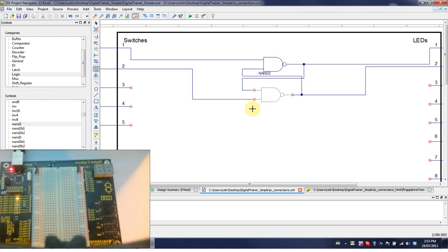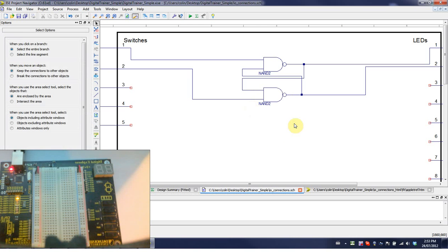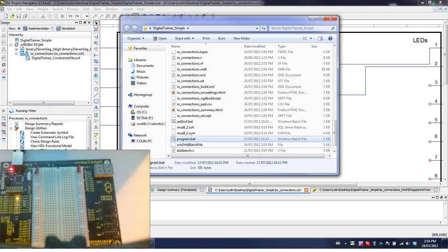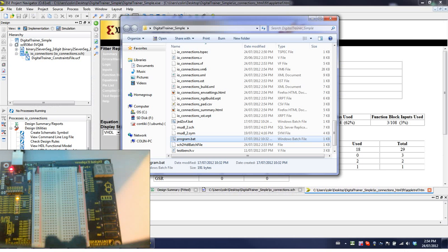So when you do this, I'll warn you that the outputs or inputs, they may not be the same. Part of the lab is to discover what they are, or you can look up online. Again, every time you change something, you have to rerun implement design, and you need that green check mark by generate programming file. Once you get a green check mark here, you can rerun the program file. So we'll just wait for that to finish, and we'll rerun the program.